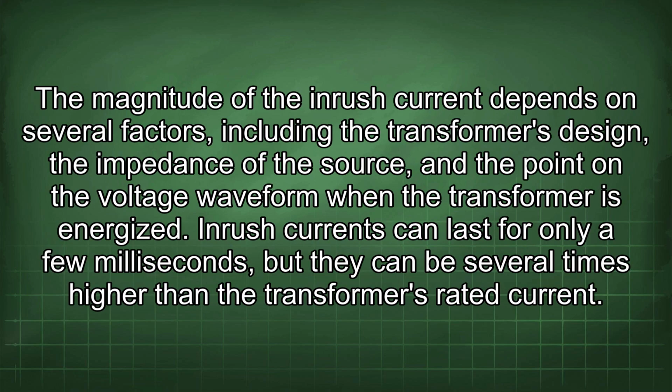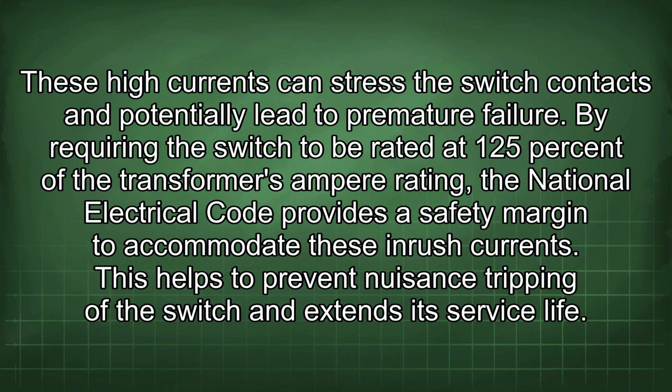The magnitude of the inrush current depends on several factors, including the transformer's design, the impedance of the source, and the point in the voltage waveform when the transformer is energized. Inrush currents can last for only a few milliseconds, but they can be several times higher than the transformer's rated current. These high currents can stress the switch contacts and potentially lead to premature failure. By requiring the switch to be rated at 125% of the transformer's ampere rating, the National Electrical Code provides a safety margin to accommodate these inrush currents.